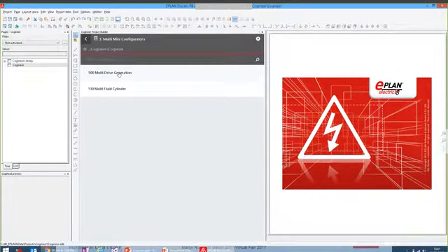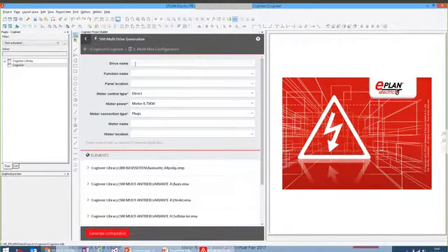We have a multi-drive generation. Imagine you, as a system integrator, you want to generate or you want to store knowledge in our systems to say, okay, I want to have a drive. And this drive is, for instance, a drive which is doing transport. I have the selection to choose a function name. I can also say, okay, I want to store it in location 01. And which is the type I want to use. In this case, I want to have a direct motor control with the power of this selection. Let's use this one. And we make the connection via terminals.